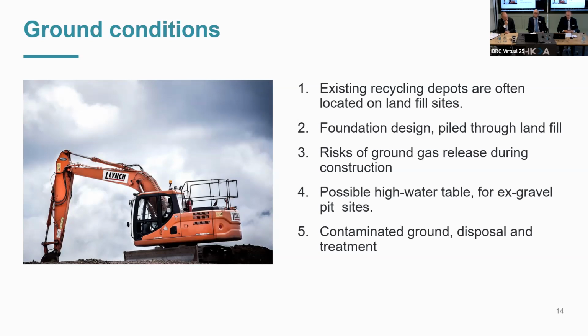And obviously, as you're digging through this material, you're going to come through contaminated material, and then you have to be very careful, as if you're working for the contractor or as a contractor, to ensure that that is clearly covered in your contract, because every time you start disturbing the ground, if it's contaminated, then you're at risk of having to process that contaminated material. And processing contaminated material becomes very expensive. If you have to send that into trucks, truck it to a processing plant, have it decontaminated, and then brought back, it is a very expensive process.